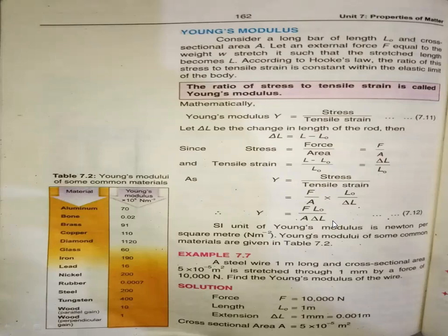Now we find the SI unit, the system international. The unit of Young's modulus is Newton per meter square, because the length unit is meter, and this meter will be cancelled with this meter. The force unit is Newton and the area unit is meter square. So our Young's modulus unit will be Newton per meter square. By using this formula, capital Y is equal to F L naught over A delta L, I solved the example